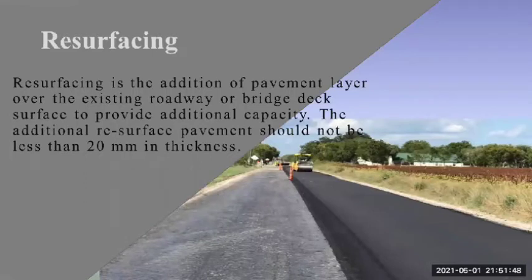Resurfacing. Resurfacing is the addition of a pavement layer over the existing roadway or bridge deck surface to provide additional capacity. The additional resurfacing pavement should not be less than 20 mm in thickness. It is to create a smooth and new surface.